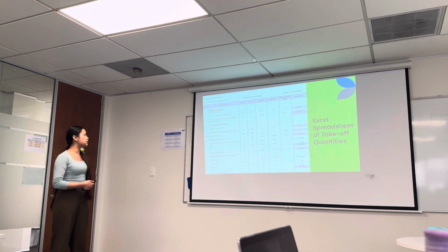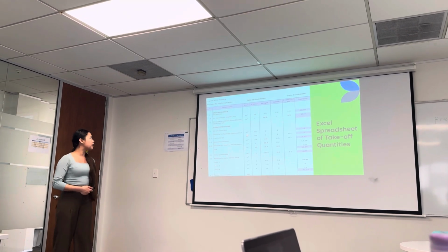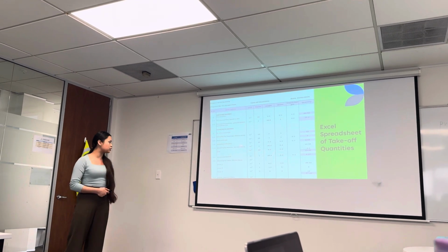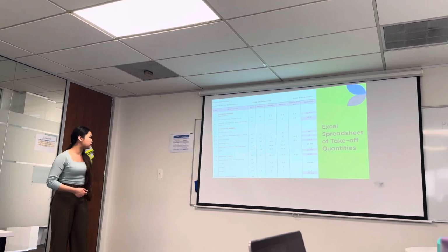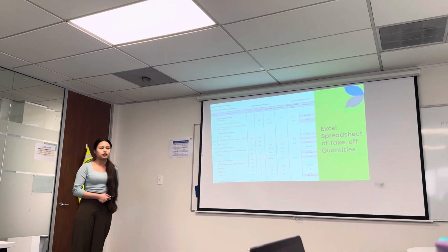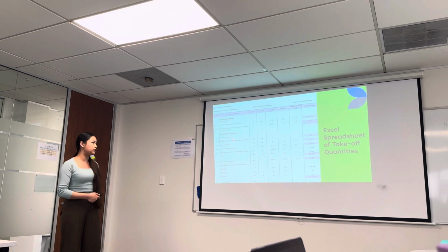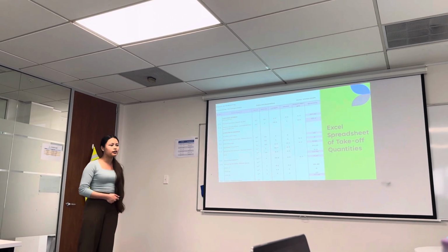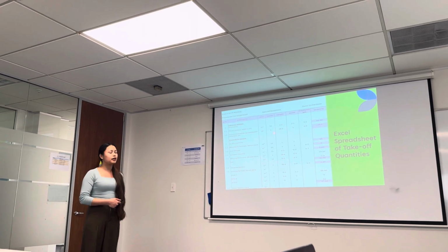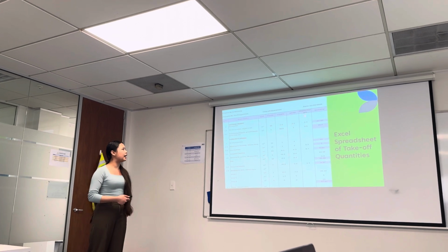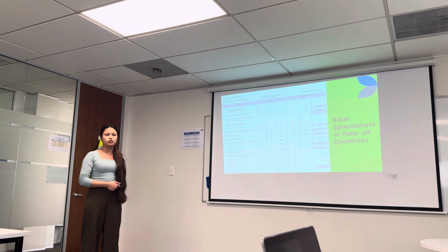As you see, the groundworks have meter cube and the concrete works have meter cube, but the blinding works have meter square, and attached beams also, all this stuff has meter cube, the formwork has meter square, and the bar bending schedules are measured in ton. So the factor is the number, that is how many times they are coming, and the length, width, and depth we take from the drawings.